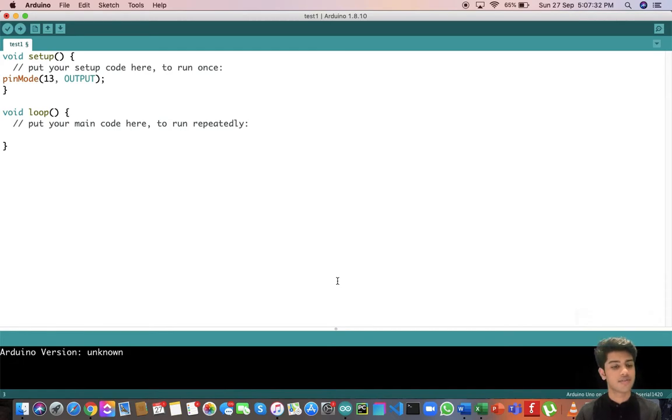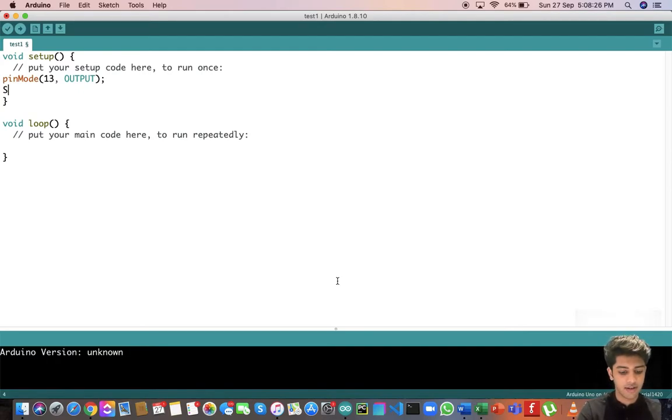So our code is rather straightforward. What is the syntax over here? First of all, we'll be starting our serial communication, which means we'll be initializing serial communication at baud rate 9600. With that out of the way, let's go to the loop section. First of all, we'll be writing a while loop to see whether serial data transmission has begun or not. So while exclamation mark Serial.available semicolon. The microcontroller will stay at this statement until any serial data byte is received.